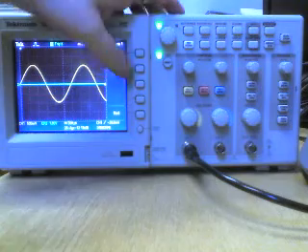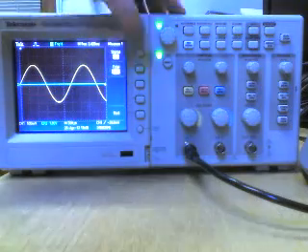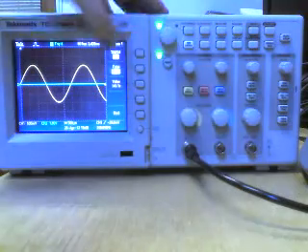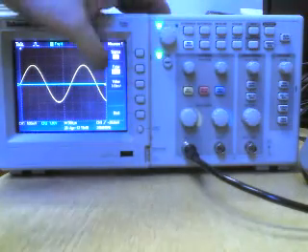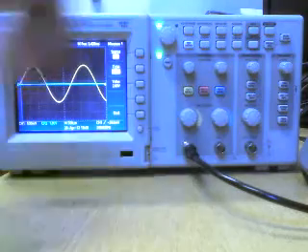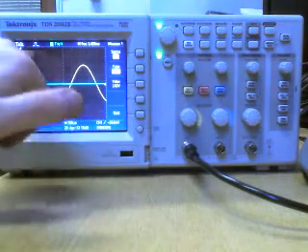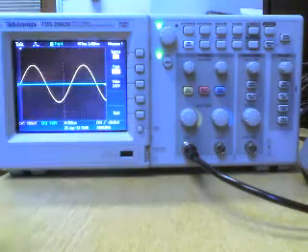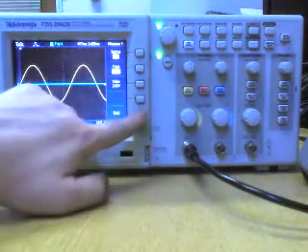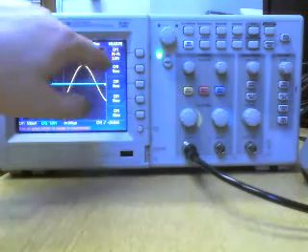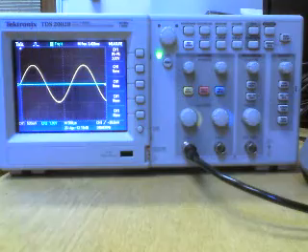And you can change the type, which is the next button down, corresponding to the next block. You can measure, say, the frequency, or the period, the mean, peak to peak, and so on. So, like I said before, we measured this as being 2 volts peak to peak. It's in actual fact 2 volts peak to peak. Hit the back button. If you press back, it's actually stored up here. This is peak to peak. It will continuously measure it.